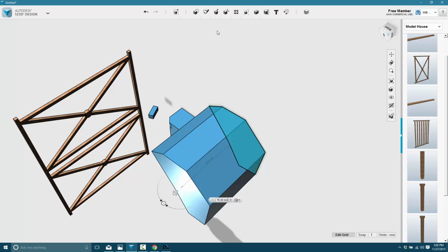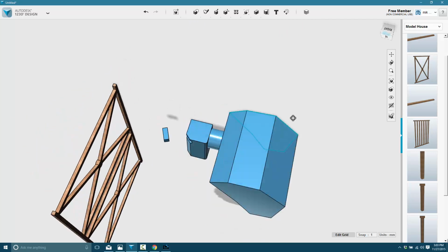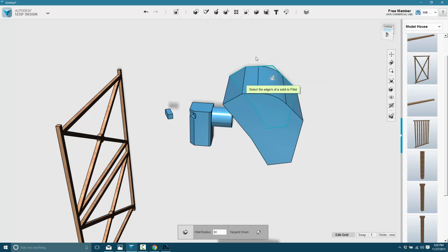And of course, it didn't have to be straight edges. We could have come in here and used splines and gotten a much smoother corner. Or we can use the filleting tool. We can make this shape a little bit smoother here using the fillet tool as well. So we come in here, go fillet. We have the edge we wish to fillet and modify like so.